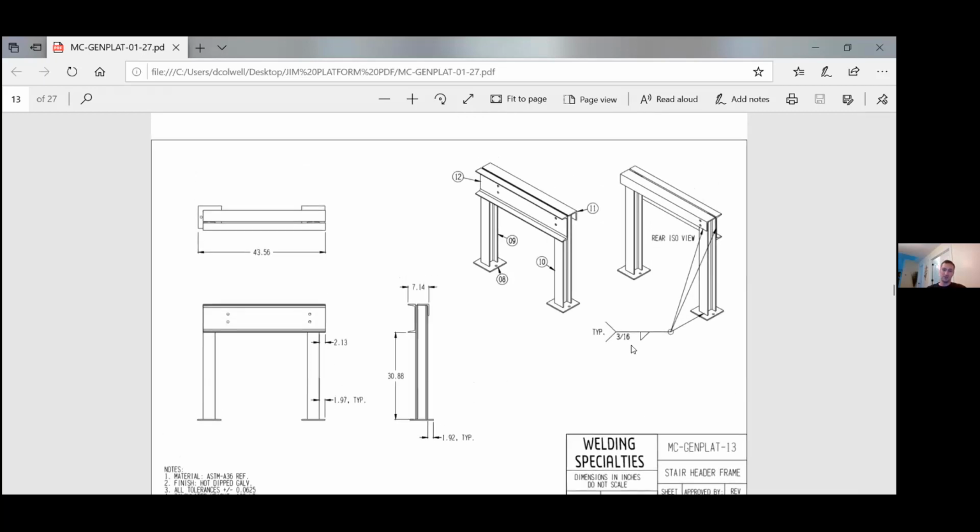I personally like to do weld callouts on an isometric view, but it certainly isn't required. A lot of times you'll see them done on the standard drawing views, your two-dimensional views. I don't know, isometric views just seem to be a better place to show it, because you get to see things, but it's certainly up to you. Just keep in mind, you've got your near side, your far side. And, of course, this is a fillet weld. You have symbols for bevel weld, symbols for butt weld. This symbol tells them what type of weld.